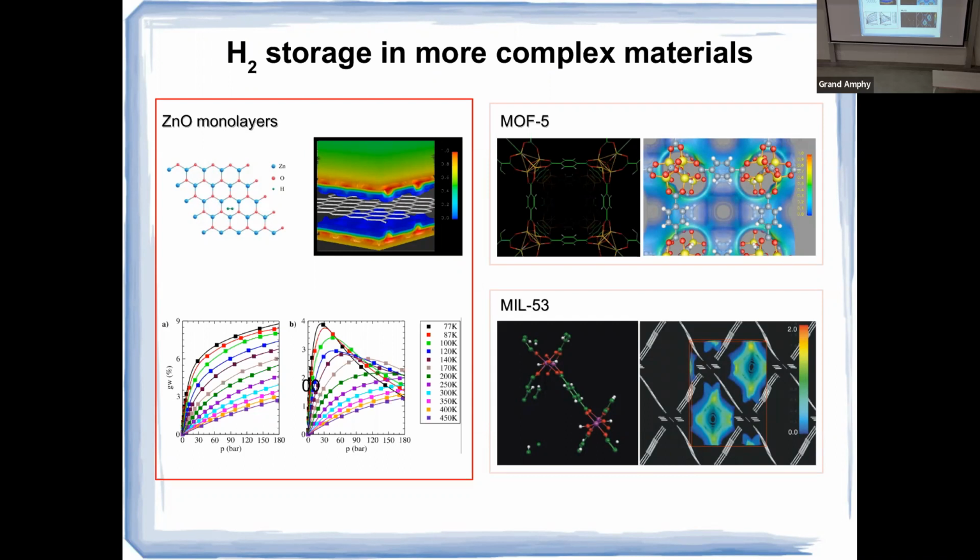And then you can know also, at a given temperature that you want to work at, the optimal external gas pressure that allows you to take full advantage of the presence of this absorbing material. And then we have also run calculations for more complex materials like metal organic frameworks that can absorb significantly higher quantities of hydrogen.